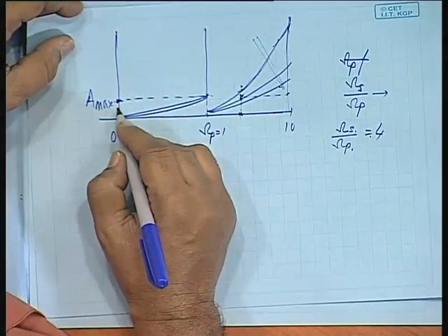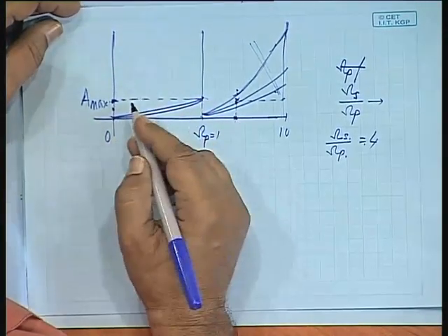A max will have to be given. So, they give 0.25 dB, 1 dB, 0.5 dB and so on. So, these are specified and these curves are available. You can always select the particular value of n and design the filter. We will stop here for today.